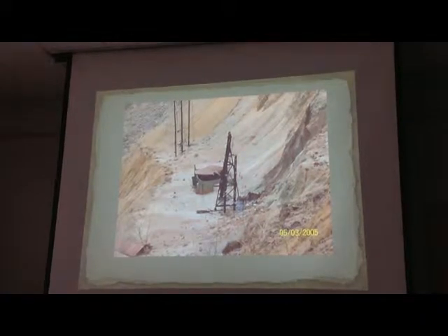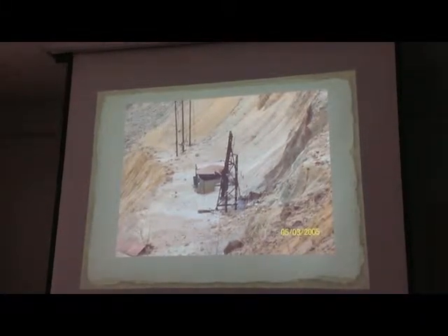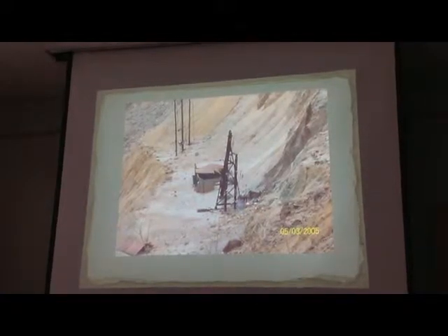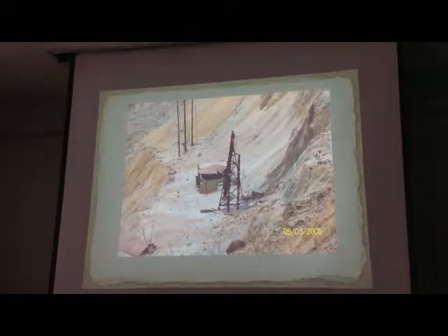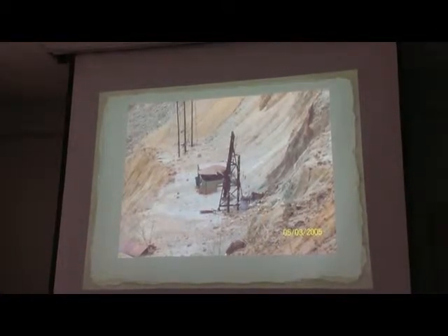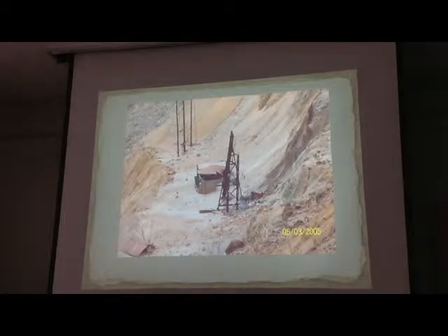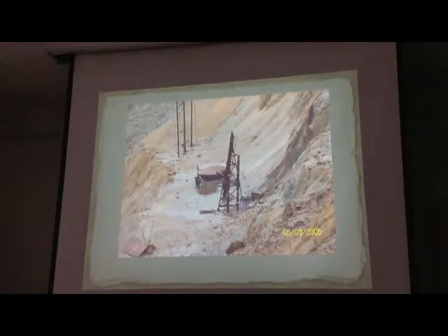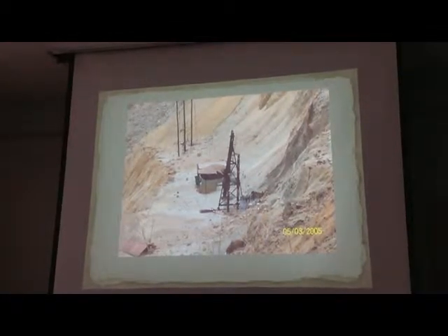Now, once more, this is the Parnell head frame in the pit. This is a tripod head frame. We've got the two front legs and then the main structure that carries the sheave wheel. Even though this was a maintenance class, this is about the only steel tripod I've seen. Now you notice the similarity to the Nunchuck head frame, just different materials. Easy to erect, easy to put up, and easy to move when you had to.